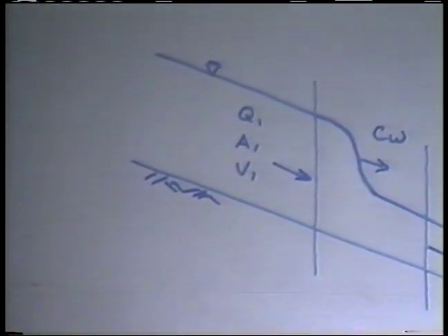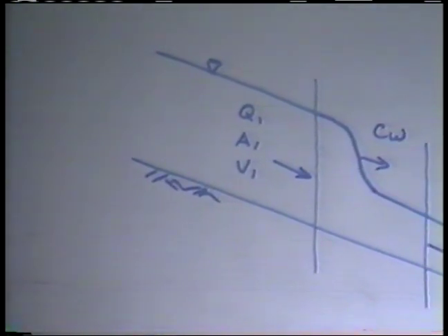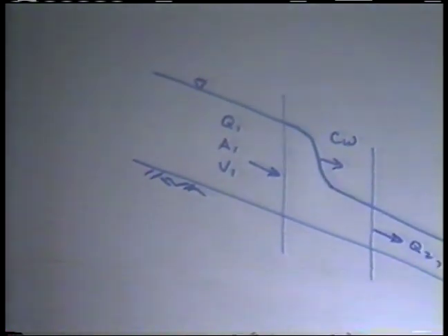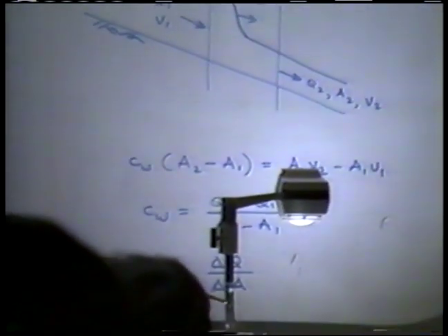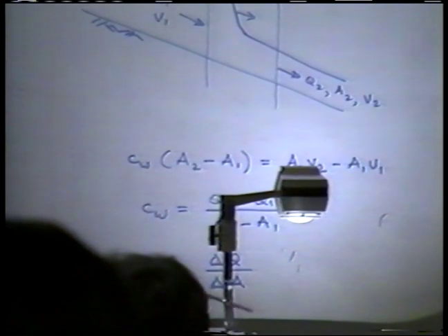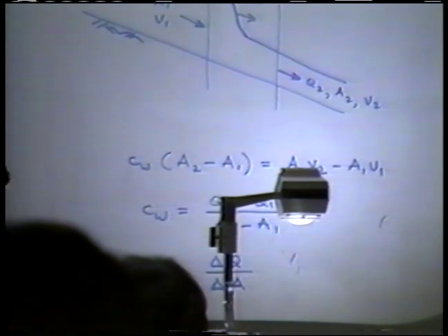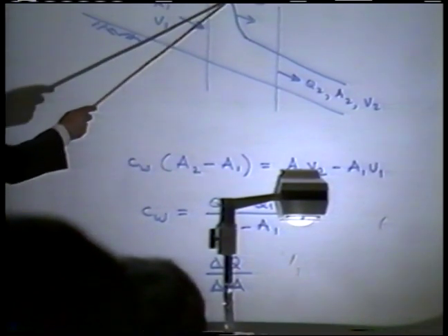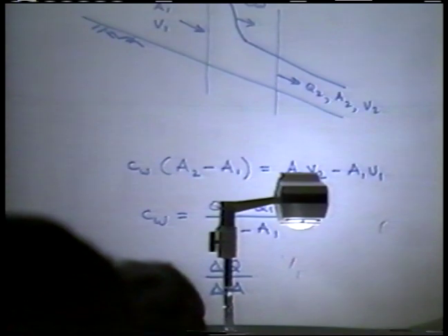And he said, if we have a wave that is monoclinal, that is just a wave that is rising, it is not receding, okay? And he went about this calculation, which showed in a rather straightforward manner that there was a velocity to that wave, different from that of the flow. And then he called that velocity the celerity, to distinguish the fact that what we're talking about here is the velocity of the surface as opposed to the velocity of the mean flow itself.